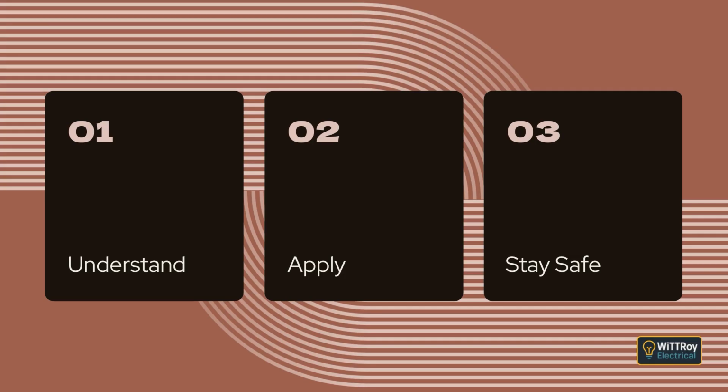Clause 3.5.2, Neutral conductor. This clause describes how to select the minimum size of the neutral conductor. For a single-phase 2-wire circuit, the neutral must have a current carrying capacity at least equal to the active conductor, or large enough to carry the total current if more than one active conductor is involved. For multi-phase circuits, the neutral must be sized according to the expected neutral current.